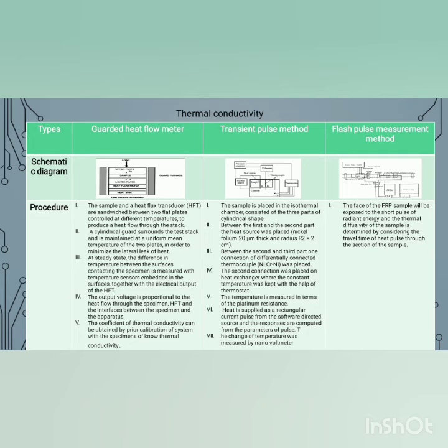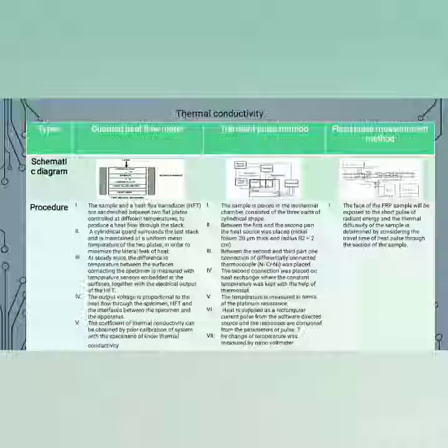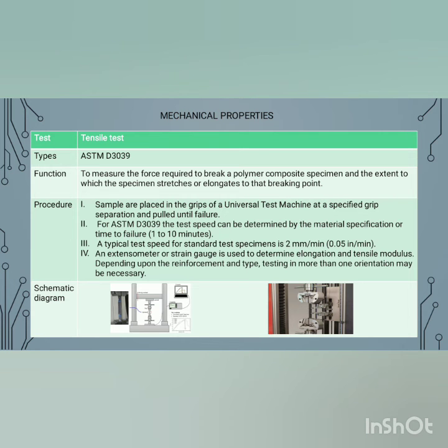Finally, for the flash pulse measurement method, the face of the FRP sample will be exposed to a short pulse of radiant energy, and the thermal diffusivity of the sample is determined by considering the travel time of heat passing through the section of the sample.